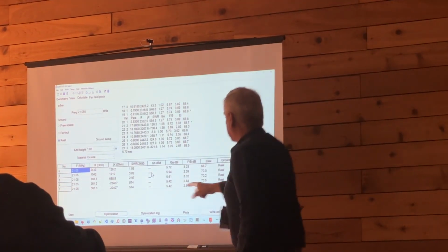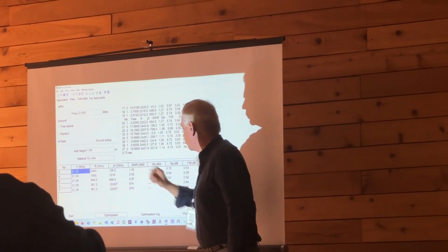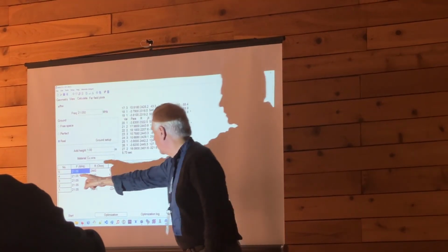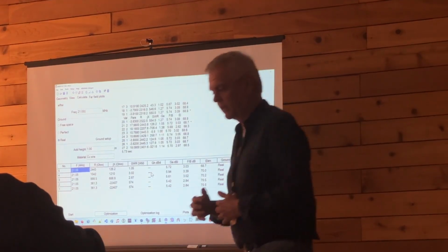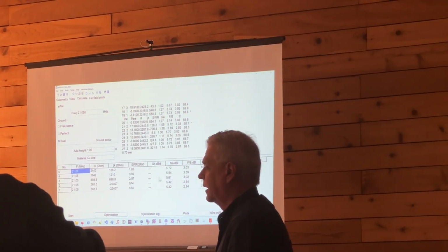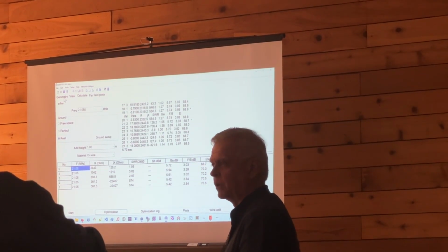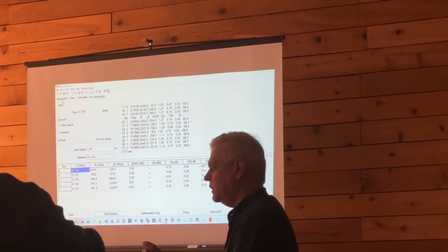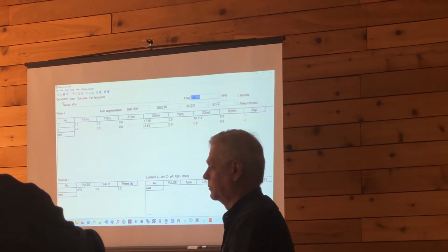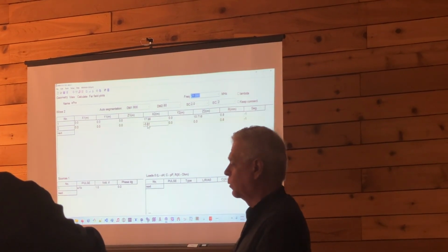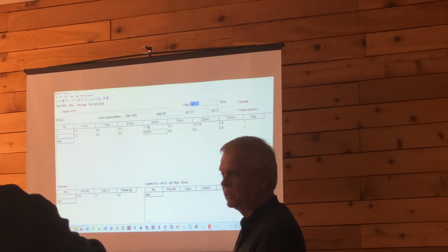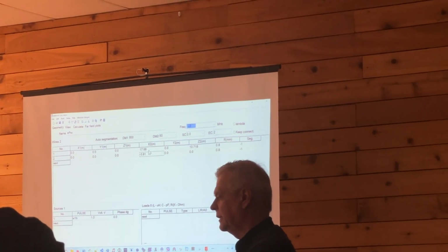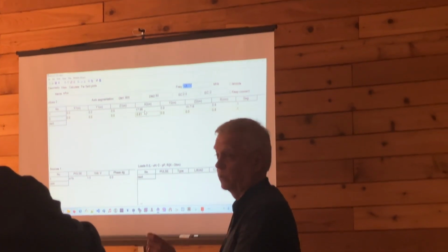Okay, so what do we get now? Good news. We got SWR at 2450 of 1.05 and our input impedance of 2443. So we should be pretty close to the mark. Well, are we? Let's see what it did to our geometry. Remember, when we tell it to optimize, it will actually change our geometry. Okay, it hasn't touched our wire 2. Good. And remember, X2 was 17.68. Now it's telling us, hey, the math works better if it's 17.98.